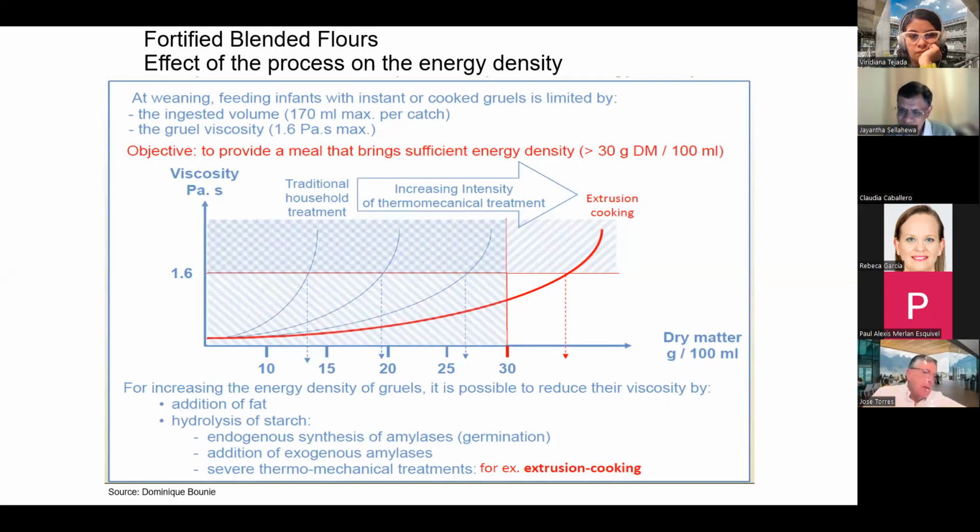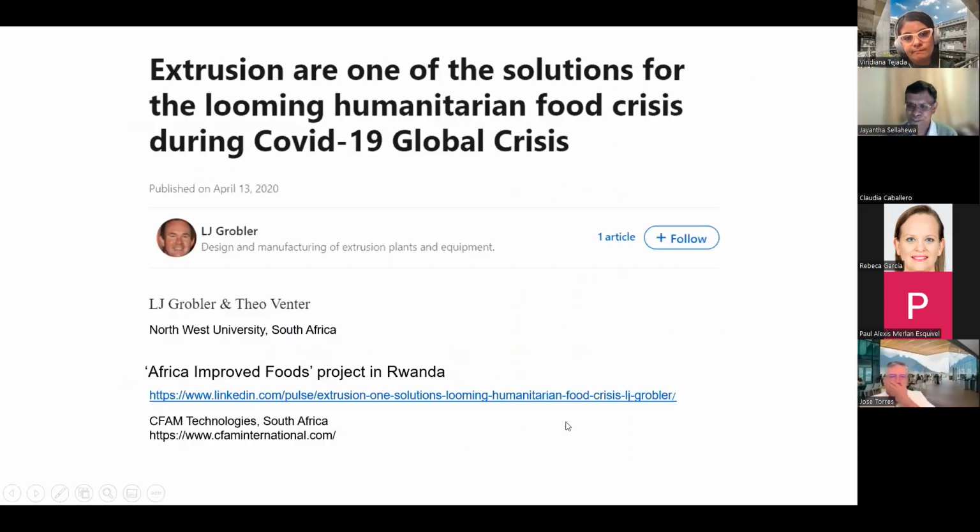but that's not the case, because this process can be done with a single screw extruder. Yes, twin screw extruders are sophisticated machines and they're expensive, but single screw extruders are relatively cheap, and also you can get a very high throughput. You can produce about 2 tons per hour. So the cost per unit in a single screw extruder is quite affordable.